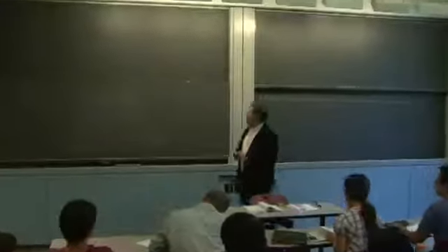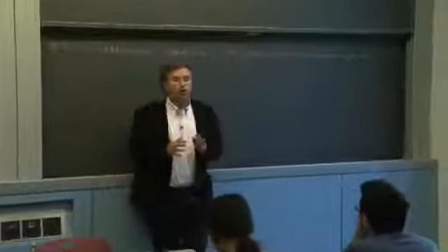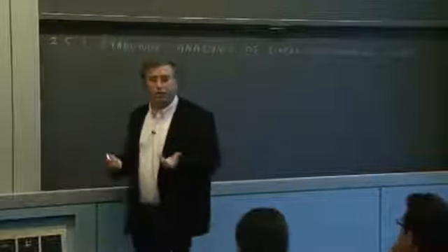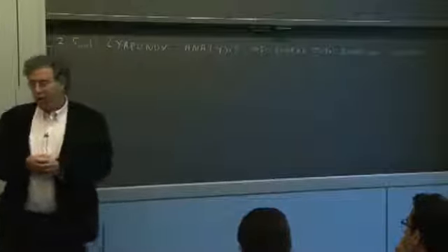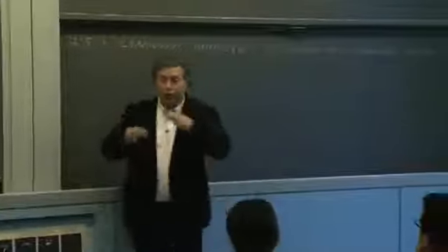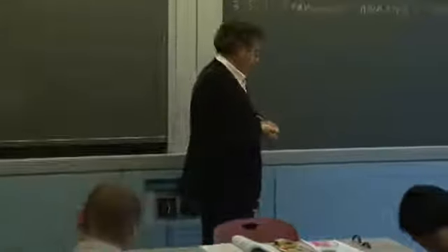Welcome back. Last time we looked at how to use invariant set theorems to look at convergence to different kinds of final behavior. And we looked in some detail at an example of convergence to a limit cycle, showing how we could show global convergence to a limit cycle by applying first the global invariant set theorem, which was telling us that we converge to the limit cycle or to the origin, and then on top of that applying the local invariant set theorem, which told us that unless we started exactly at the origin, we actually converge to the limit cycle.